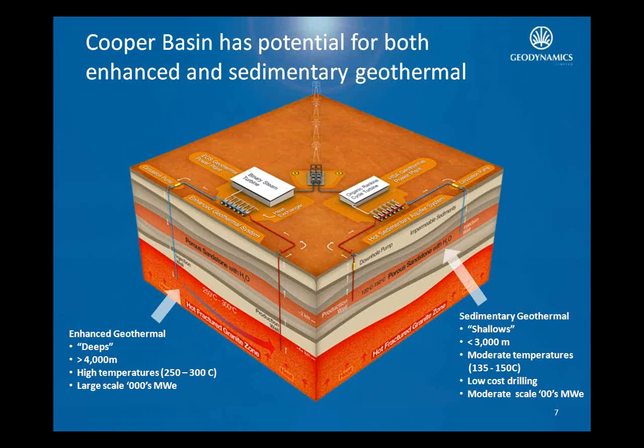and the water through that sandstone flows quite readily. It is at a lower temperature, and we're looking at sort of 120 to 150 degrees C water within that aquifer, but it's much easier drilling. It's much easier to drill down to those depths. You can extract the heat in a very similar way. We use a slightly different process to extract the heat because it's a lower temperature, but that system is very similar. But it's water that's come from an aquifer. The heat gets extracted and gets put back into that aquifer.